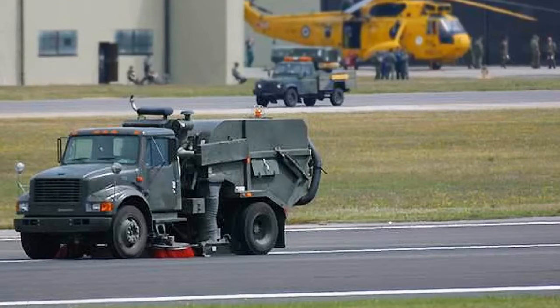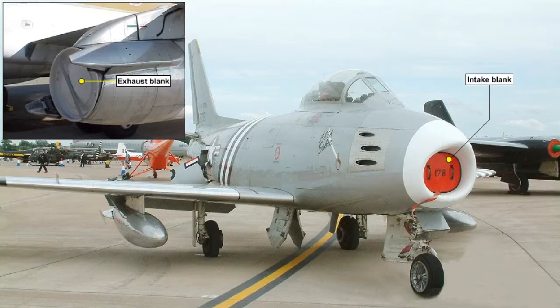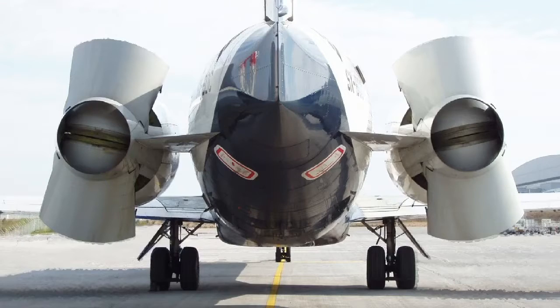To prevent damage occurring from foreign object ingestion, it's essential that the operators of gas turbine engines should take precautions which preclude the entry of debris into the ramp area. After flight, intake and exhaust covers should be fitted to prevent ingress of contaminants and also help to prevent the engine windmilling. During engine startup, aircraft taxi, and engine reverse thrust operation, debris can be sucked into the intake. Engine power should be kept to the minimum required to avoid damaging it.